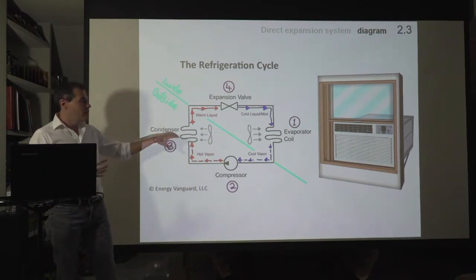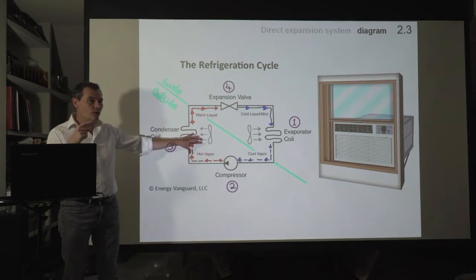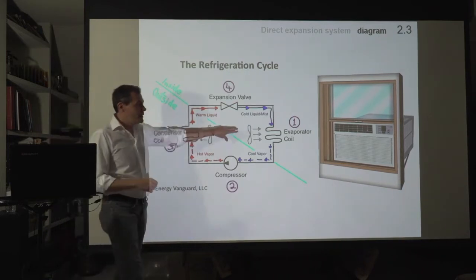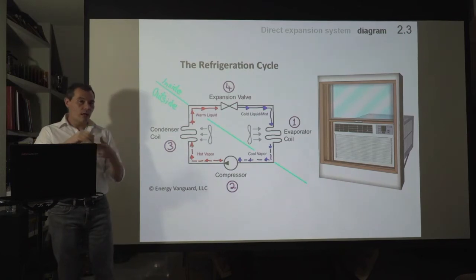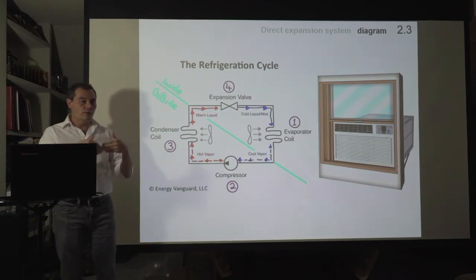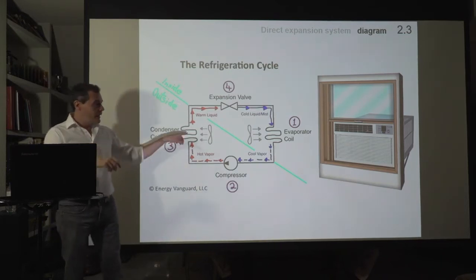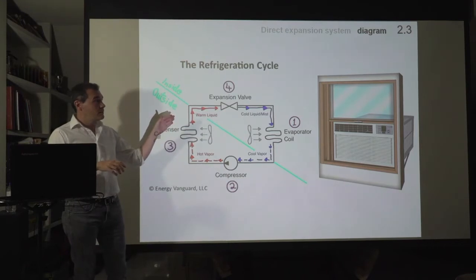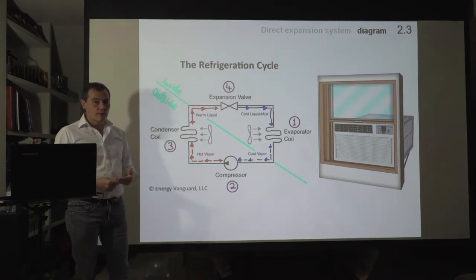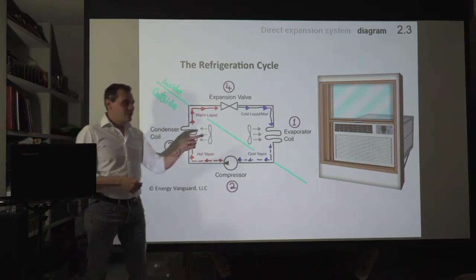So we need something to generate the energy, and this is what we call the heat pump. And then we need something else to move that air that we have heated up or cooled down, and we need to move that air into the building. If everything is within the same box, this is the most basic air-to-air system. This is out of date.